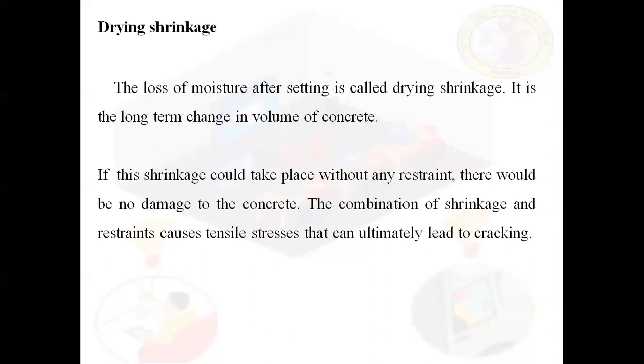Next, coming to the drying shrinkage. Drying shrinkage is nothing but the shrinkage which occurs after the concrete is set. That means it is the long-term change in volume of concrete. Once the concrete has hardened and the shrinkage occurs, in the long term that cannot be regained once again. For that we are calling it drying shrinkage.